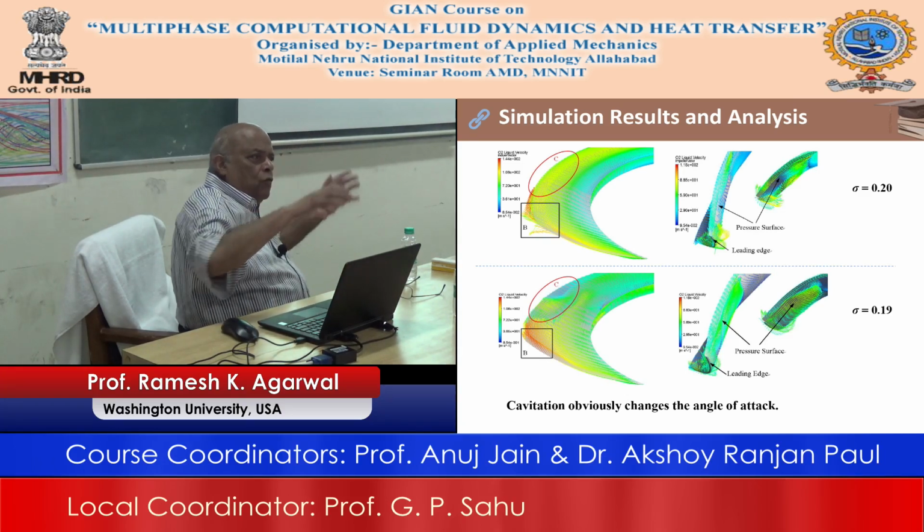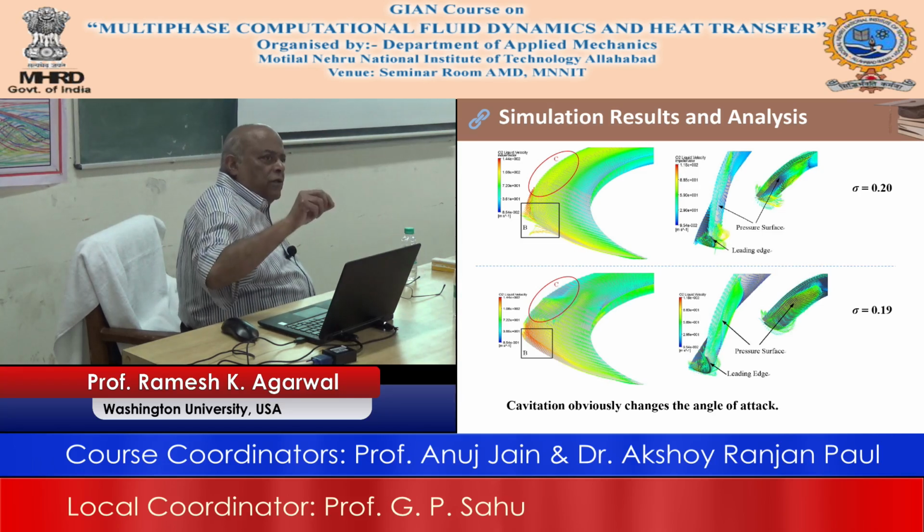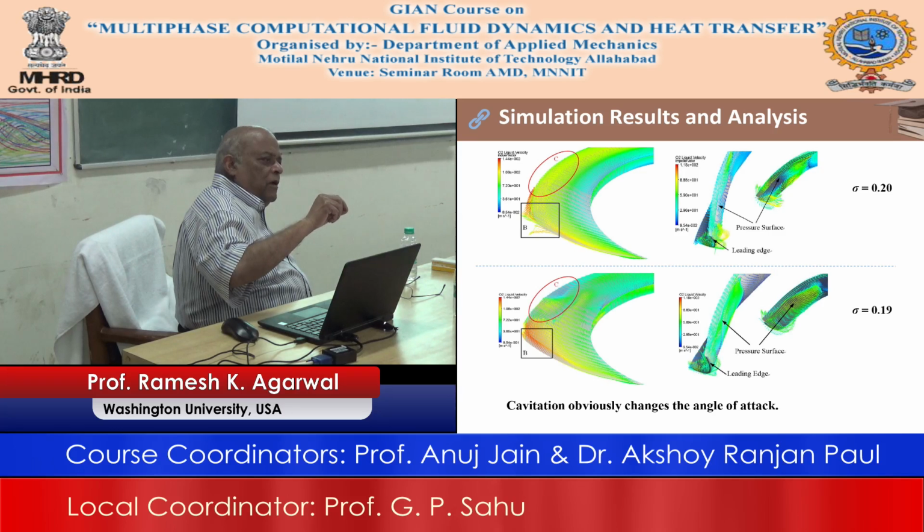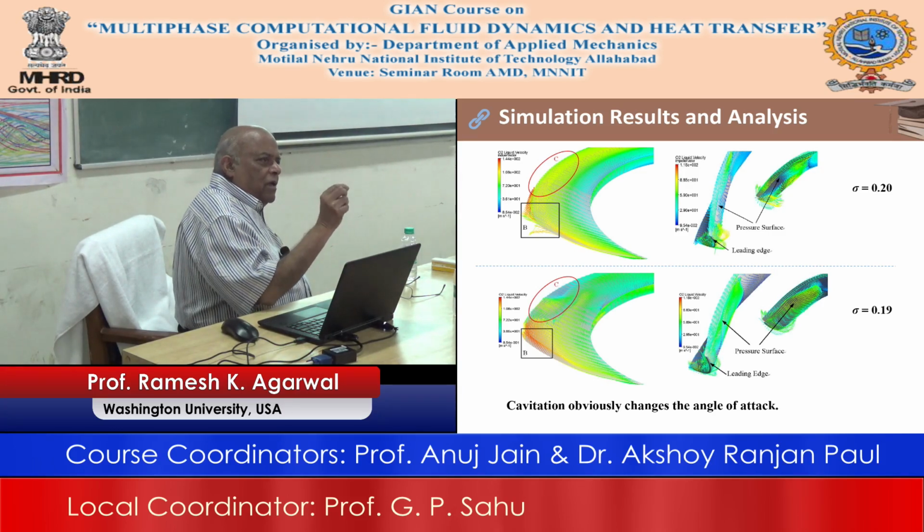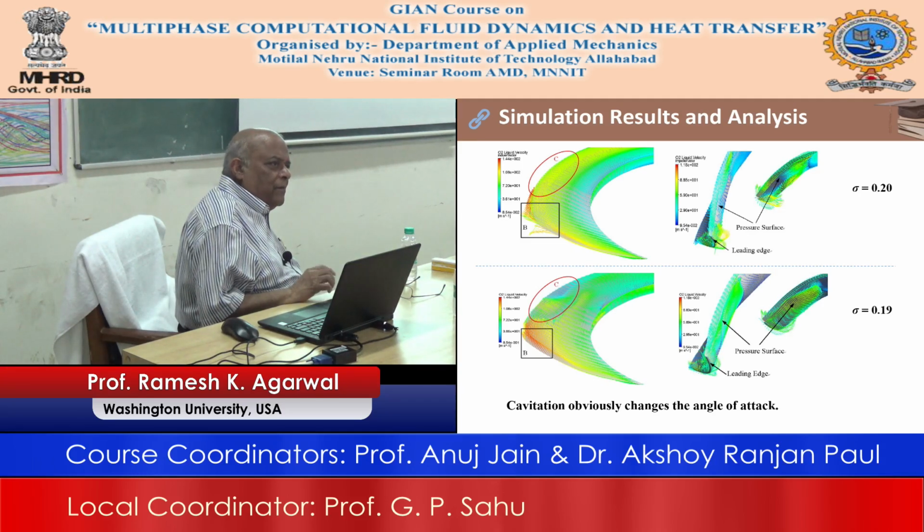This helps in identifying vortices. If you have a bunch of vortices and a velocity field calculated from Fluent and the pressure field, you take its gradient, and that will give you some idea of where the vorticity is. Now, can you tell me why the gradient of U gives you the vorticity?